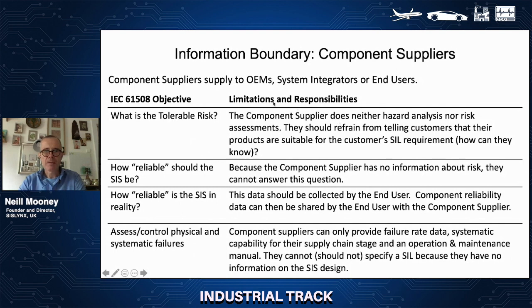So, limitations and responsibilities of component suppliers. The component supplier will do neither a hazard analysis nor a risk assessment. So they're not able to tell their customers that their products are suitable for their SIL requirement. The second point, how reliable should the SIS be? Again, the component supplier has no information about risk. They cannot answer this question.